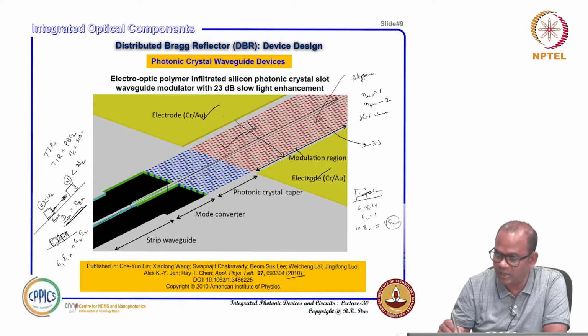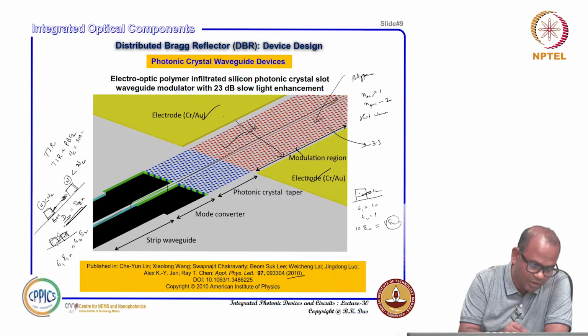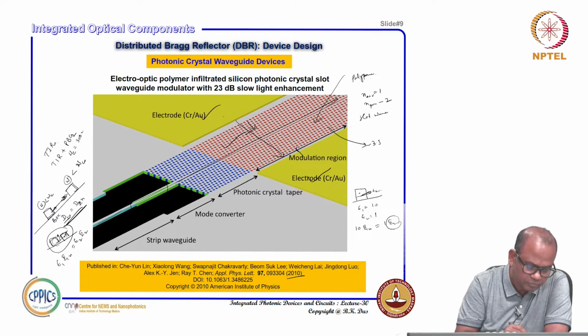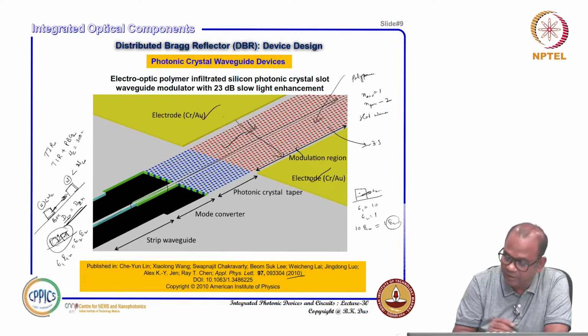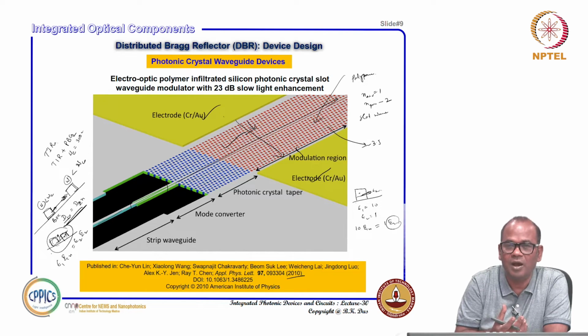That means the outside electric field will have 10 times higher strength than the inside. Similarly here, together they jointly give a guided mode, and because of the boundary condition you will see that in the gap region, where there is air, the lower refractive index region, the field strength will be high.